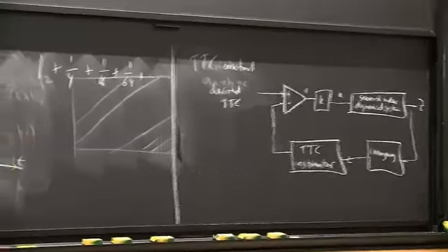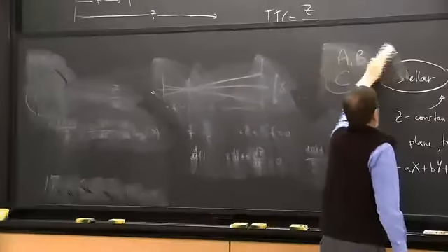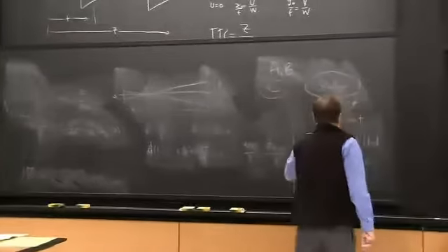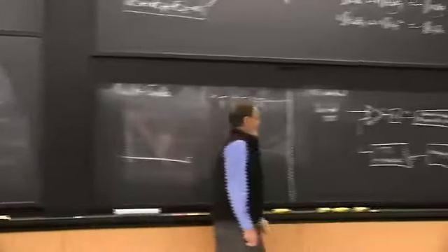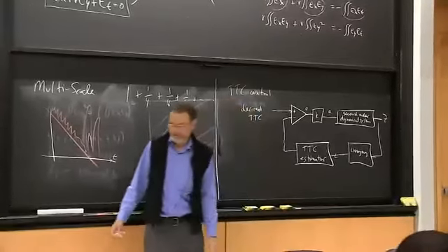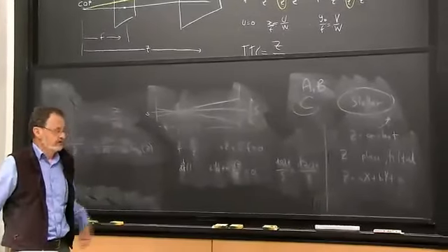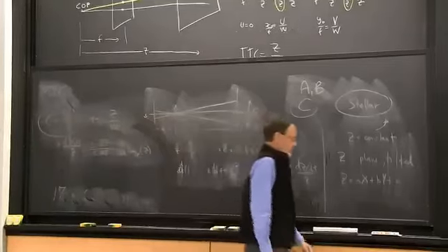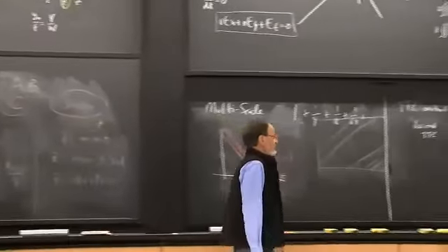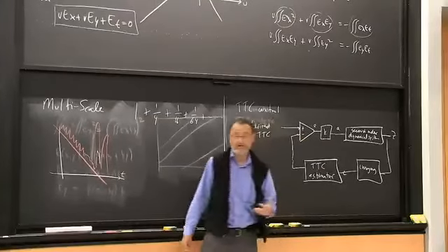So if your measurement says that at the current rate of descent, you're going to have a shorter time to contact than desired, then it'll add some more force to the engine. And conversely, if it looks like you're kind of hovering too much, you should be dropping down, then the time to contact will appear large, and then the error signal will cause you to reduce the engine output.